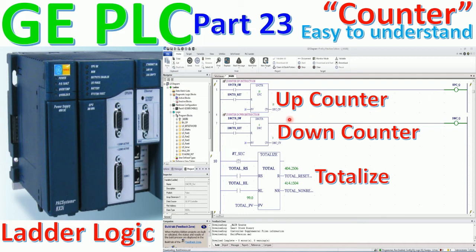Another type we use is the down counter. It is not the same as the up counter, because for the down counter, when we first scan the PLC, it will start from 20 if we set the PB to 20. When we provide the input, the counter counts down from 20 to 19, 18, until 0, and the output is turned on also. So it is the counter down. If we push the reset button, it will reset to 20.